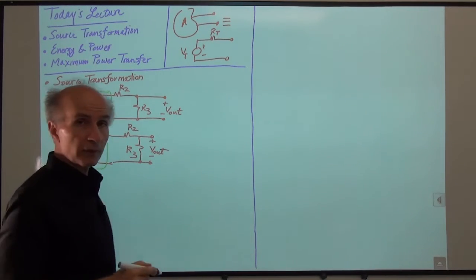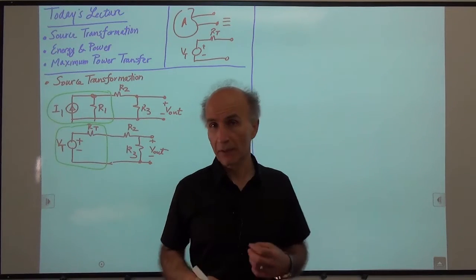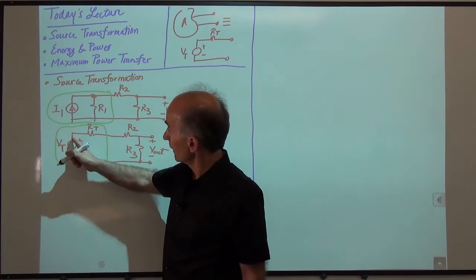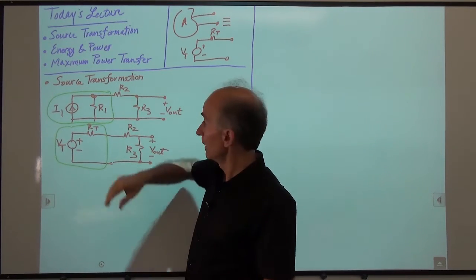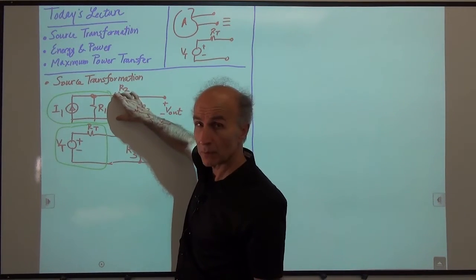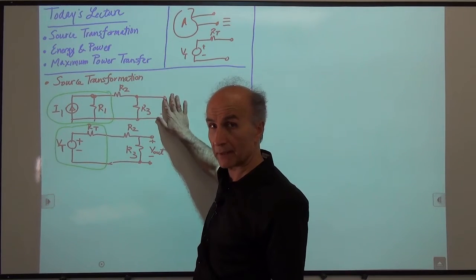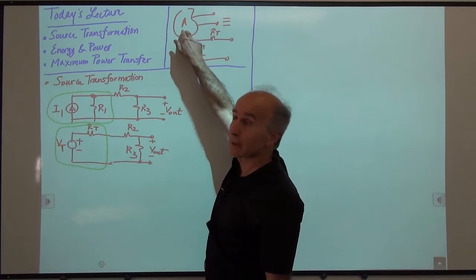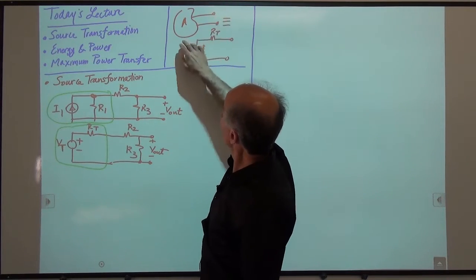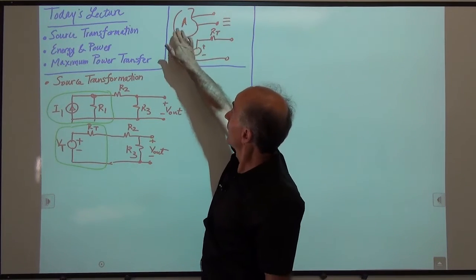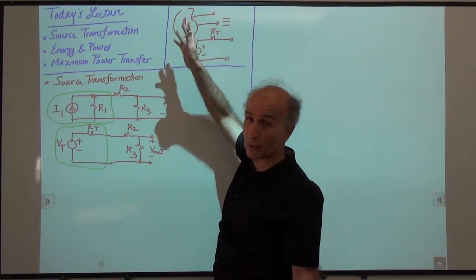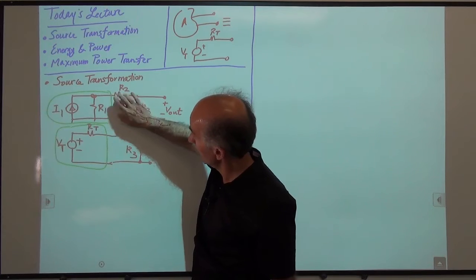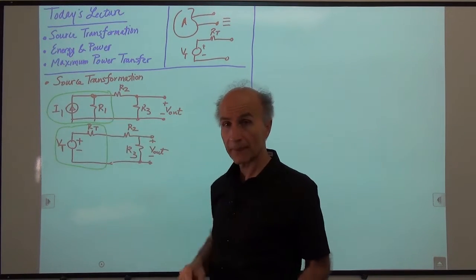Okay, so how do I go from the top green box to the bottom green box? Well, it should be easy, right? The Thevenin voltage is obtained by looking at these two wires, the voltage between these two when nothing is connected. That's what Thevenin told us, right? Thevenin said, look at the voltage between these two wires when nothing is connected and this circuit is generating voltage. We're trying to measure that. So let's focus on that and see how much voltage this little circuit generates here, right?